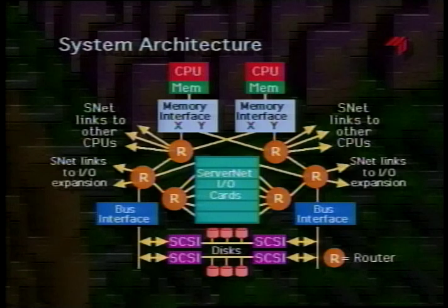When we have inbound I/O, we still have to keep the memories consistent, so the routers have a special mode where incoming I/O packets are duplicated and sent to both memory interfaces simultaneously. Then the incoming packets update both memories at the same time. If we get a failure of one of the CPUs, the other one can take over since it has exactly the same context as the failed CPU.